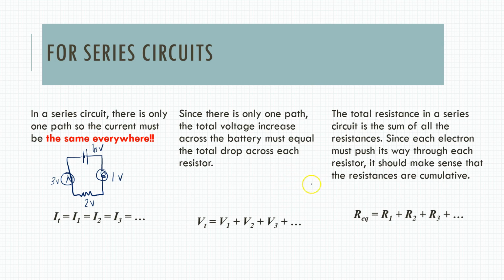You put too many things on it, because if you add one thing with a resistance of 5 ohms and another with 10 and another with 15 and so on and so forth, those all add up. Right now we're up to 30 ohms and your circuits can only handle so much. So in series, those all get added together, and that makes what's called the equivalent resistance or the total resistance. It says EQ for equivalent, which is just a fancy way of saying total.